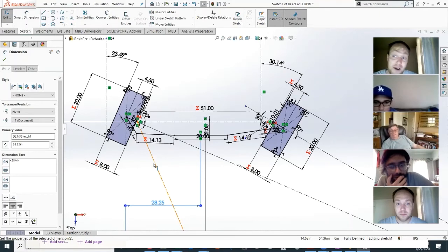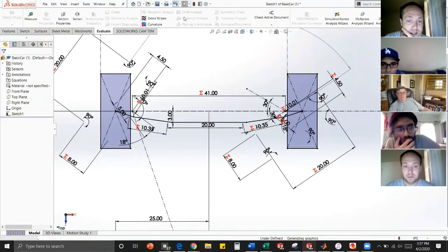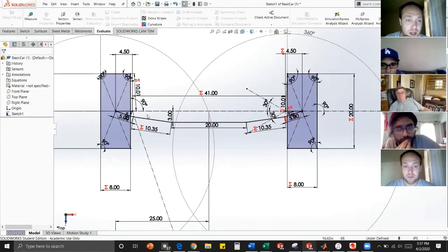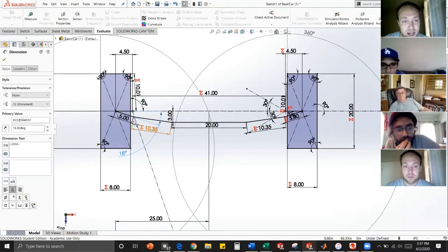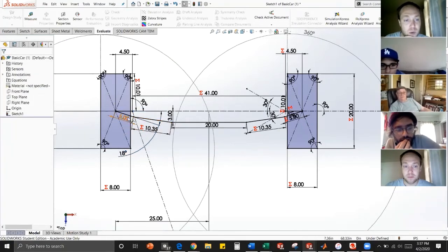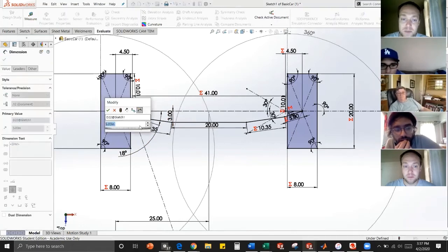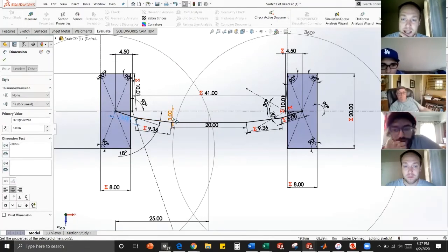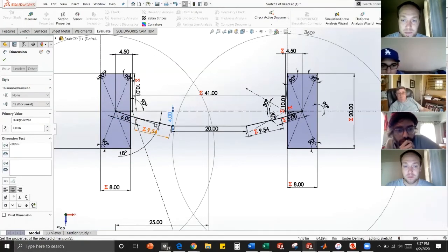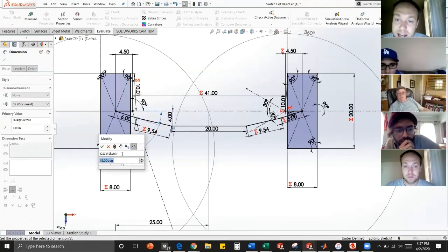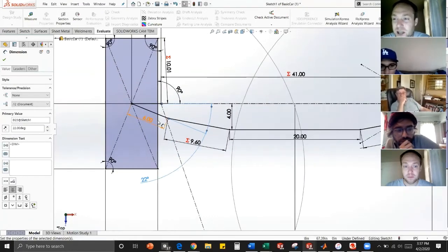There's no obvious solution, but one thing you can do is, you don't want this tie rod to be in line already with your steering arm. Keep in mind, when you turn it, you see that 6-inch steering arm? You shouldn't actually compare it to this. You should compare it to the line.